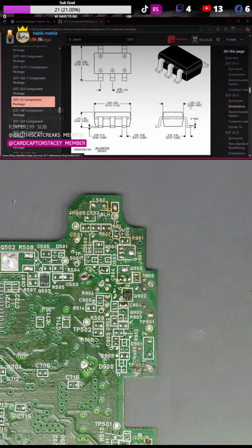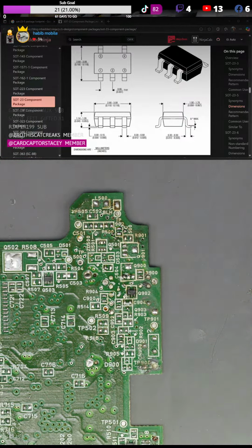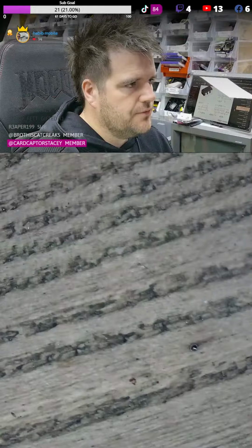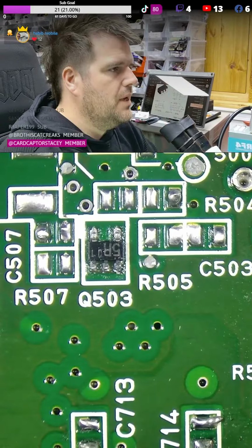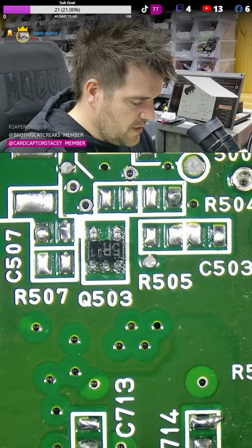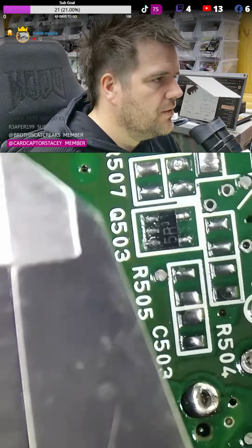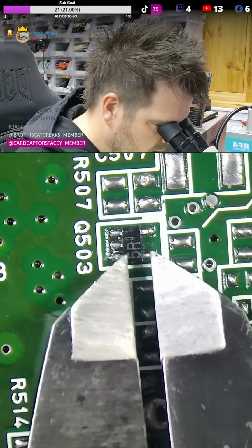So the final confirmation is just the width or the length, whichever one it's classed as. The other dimension is 1.5 millimeter. So to affirm what we think, we want to check if the black body package is somewhere within 1.5 millimeter, and then we're good to say this will be a SOT23-5.